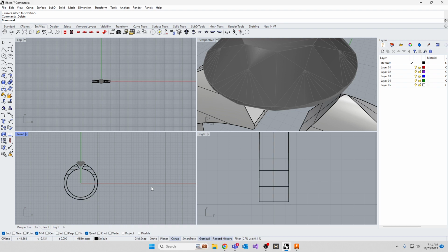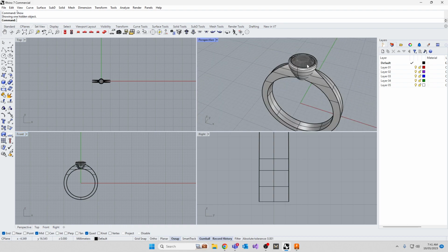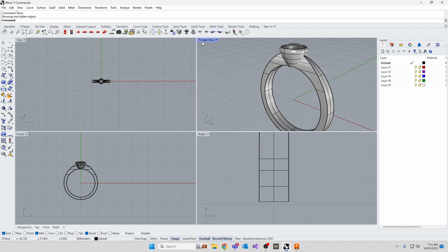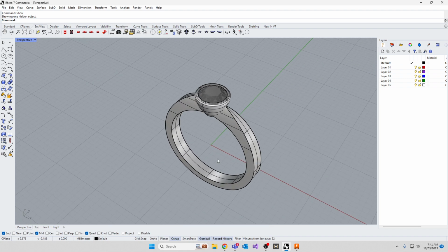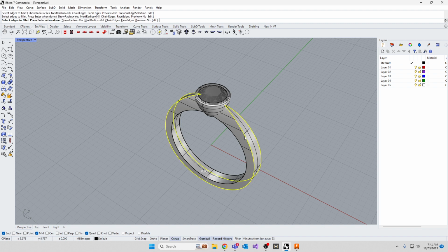All right. Let's show our collet. What do we need to do here? I want to do a fillet. I can do a variable fillet again. I don't want to go through all the trouble we went through to explode and create curves and sweeps, so I'm just going to do a fillet. Fillet edge, I'm going to say that I want it to about 0.8. And I want to do this edge and this edge.